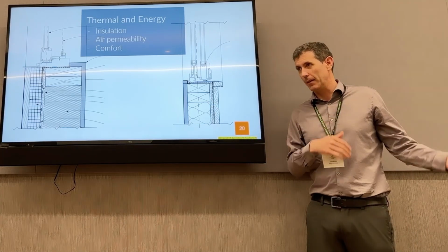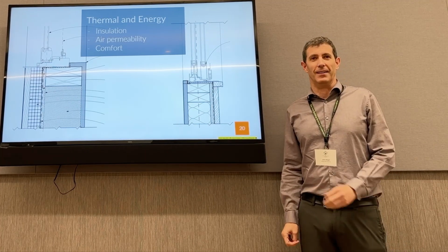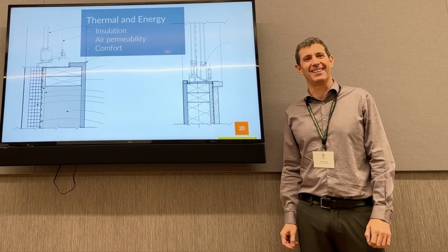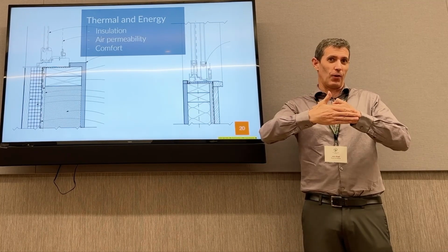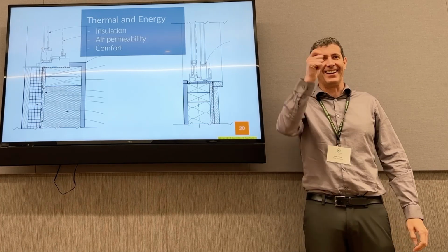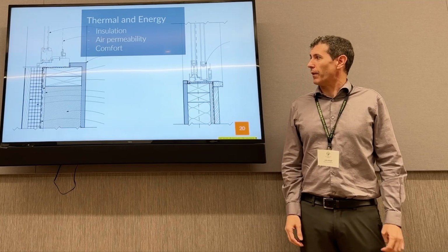Dust can come in, pollen can come in, smoke can come in. That's right. They may have had 15-pound building paper overlapped, right? They lapped it. Oh, yeah. They might have lapped it 4 or 6 inches. Nailed it, packed it. Not the wrong way. Right. So big difference.